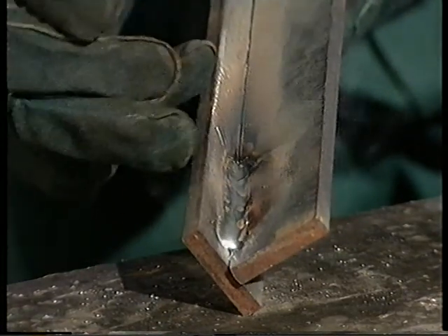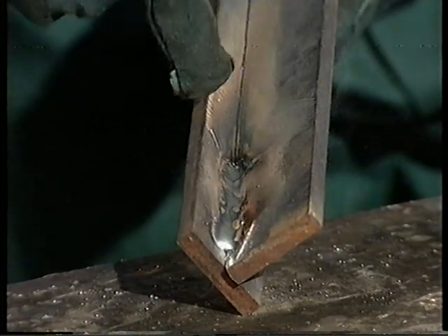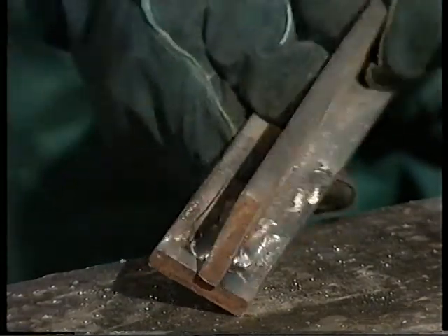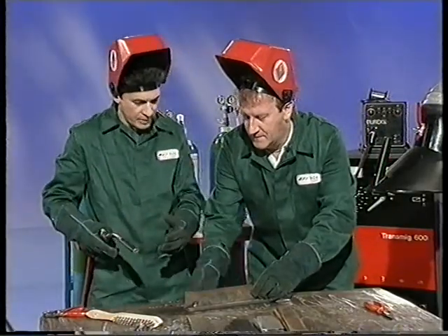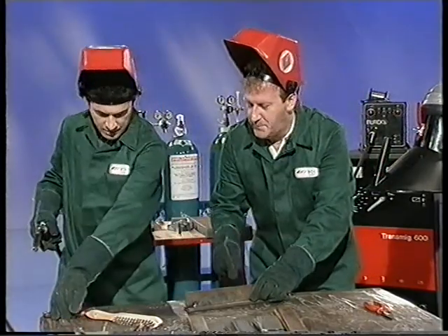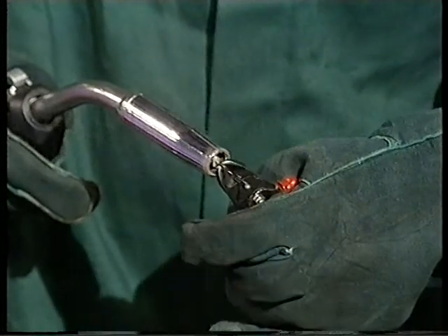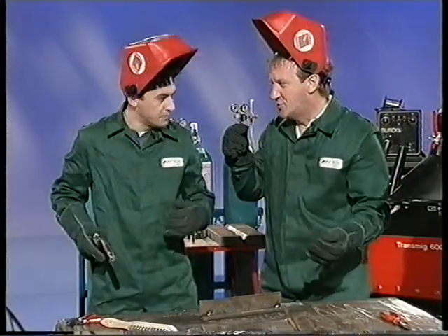The only criticism that I had was that you were allowing the torch angle to drop a little so that you were unevenly distributing the wire on the plate. I went out of control at the beginning, I think. I wasn't quite in the right place to start off. Yeah, because it's quite high amperage work, the wire is coming out quite fast, and you really do have to set yourself for the start because as soon as the wire hits the plate, it wants to force your hand away. Yes.